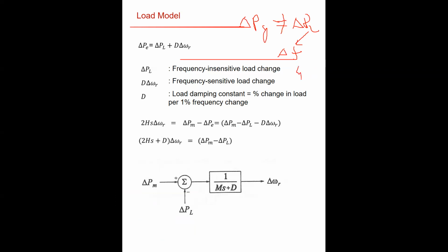This is 49.5 hertz, right? This is 49.5 hertz here. Now with the change in the frequency to 49.5 hertz, do you think the power drawn by the lighting load will change? The power drawn by the lighting load at 50 hertz and at 49.5 hertz, do you think it will be changed by the lighting load?